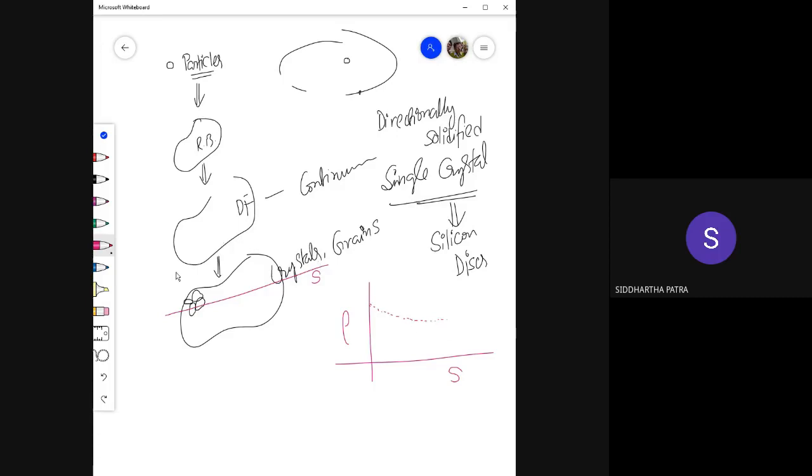And that gives us the approximation of continuum, which basically means, yes, we accept that the material has pores and holes in it, and there are discontinuities, there are grain boundaries, there are so many things, but they are just so much tinier that effectively we can think that the properties are changing continuously within the material. Not just the properties, any quantity. If the temperature has to change, that would also change from one point to the other continuously.